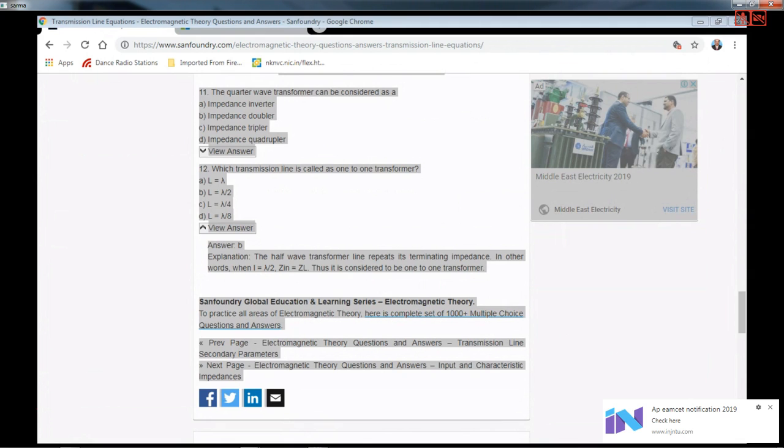though they are a bit expensive. Whereas VSWR is very easy to measure, and the instrument used for this is quite cheap. So people depend on VSWR in the first place, and once the basic conditions are satisfied and the system is established well, only in the final stage do people think of doing measurements on the network analyzer and get satisfied that the reflection coefficient values are within the specified limits. So this is how VSWR gives us a first indication of how well the system is working without any reflections. That's the importance attached to VSWR.